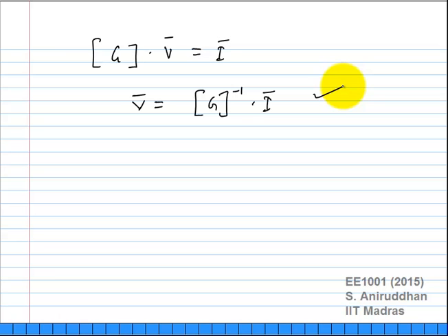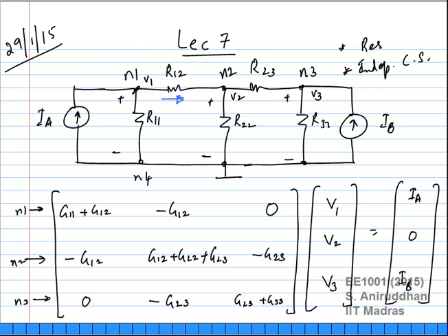Now, of course, we have taken the case of a very simple circuit, which has 4 nodes, 3 independent nodes, and only a few elements here, right? But the real power of this is that matrix inversion, or solving these kinds of equations, can be computerized. If you take an integrated circuit, for example, today, it will have probably tens of thousands of transistors, if not millions of transistors. You can actually write this down in matrix form, of elements, okay?